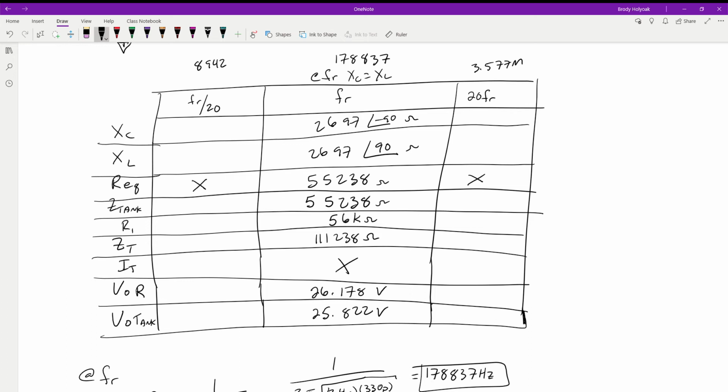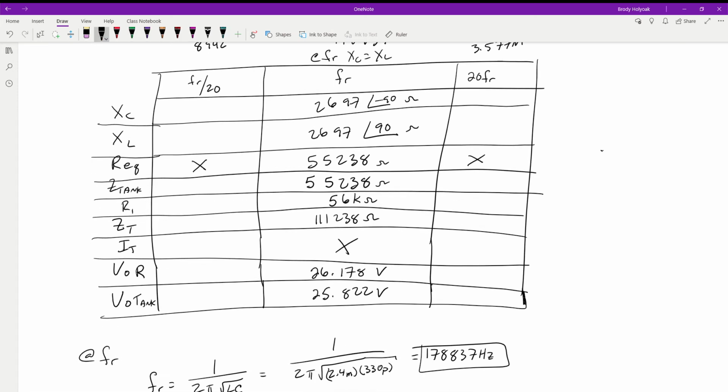So I always kind of figure, if you want a drastic change, go 10 or 20 times higher or lower than the critical frequency if you're trying to determine this as an analysis tool. You don't want to have one data point right here and the next one right next to it. With what we're dealing with, we want value points that are out here, away from the center frequency point.